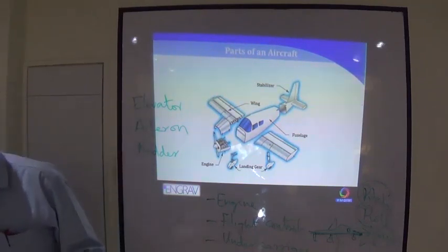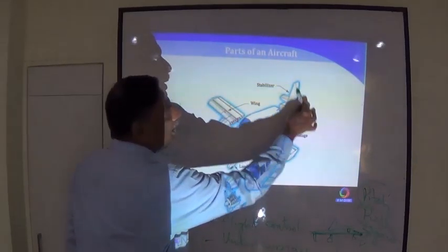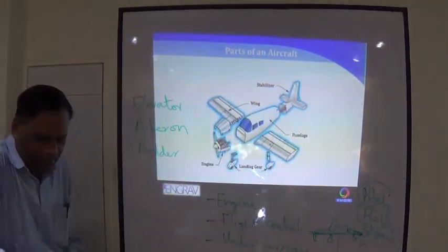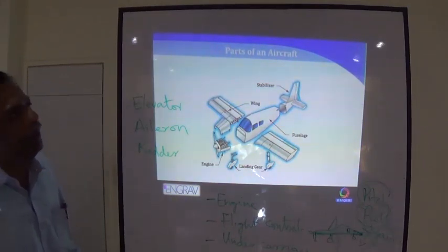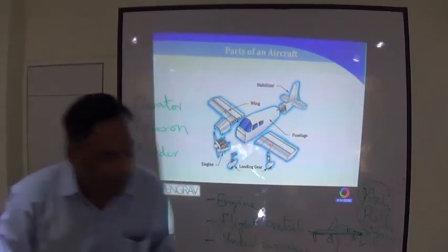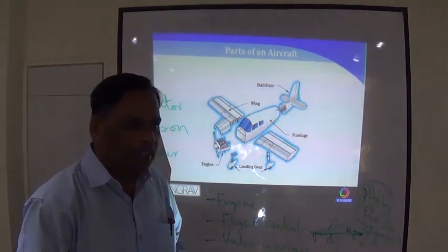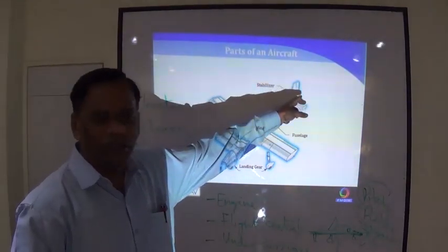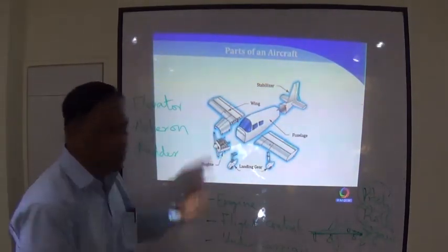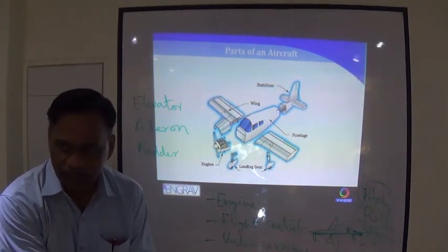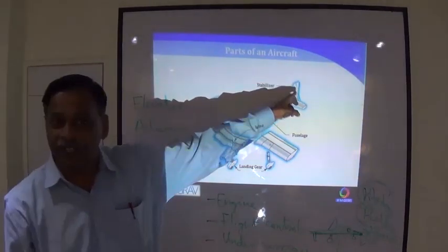You're understanding this aspect, right? Rudders are fitted on that side. The rudder is fitted here at the back end. It is hinged over there, so it has this motion. When you are coming in for taxi, let's say you landed, you have reduced the speed, you come into the taxi, then your rudder will not be effective because airflow has stopped. You are getting very little air. That's the time they use the nose landing gear to steer it, like a car or a bike. In the air, you use the flight controls.